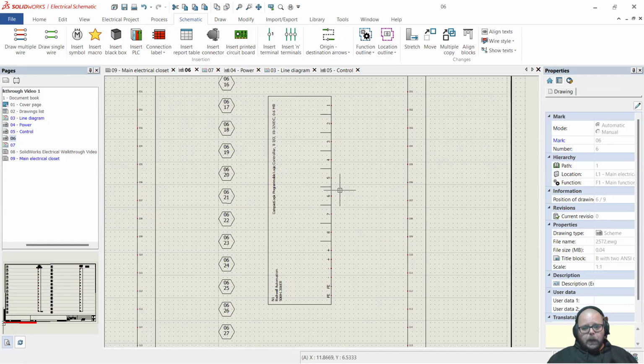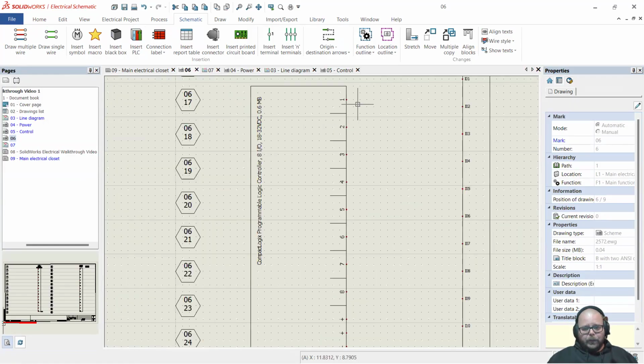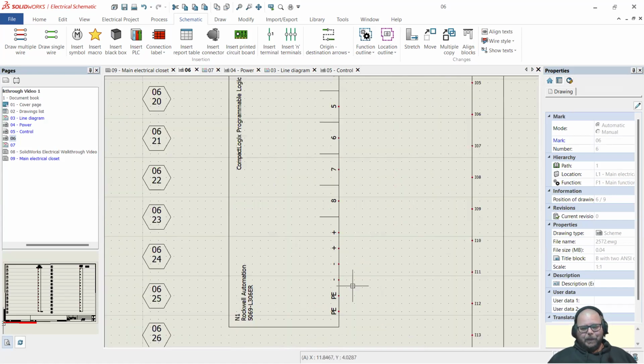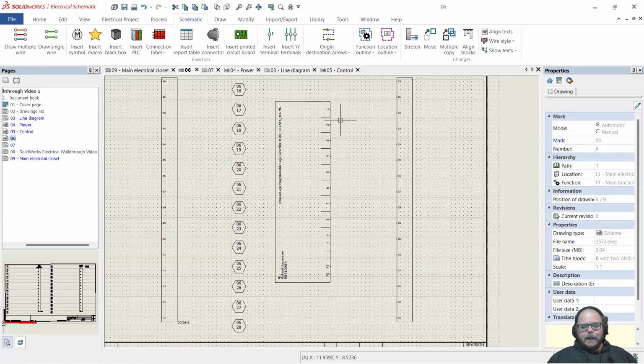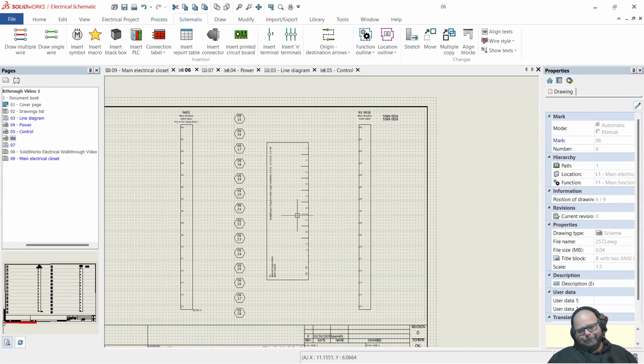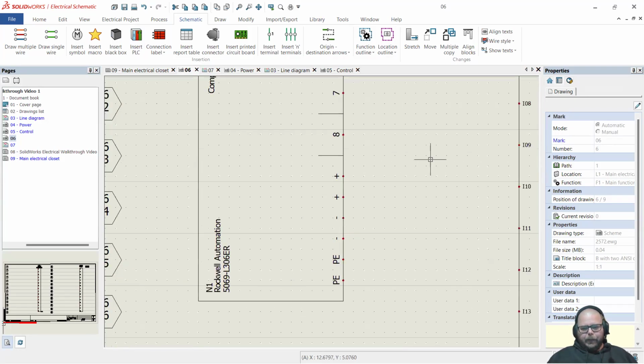I mean, these 8 terminals on this PLC, I can vouch for this personally, technically don't exist. It's really just these 6. These are the power supply to the PLC. Those 8 you could probably use for Ethernet. I've done that before, run individual Ethernet cables in there. That's getting a little picky, but at least we got the power now.